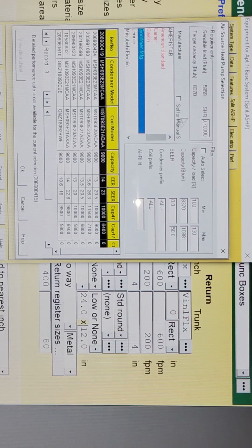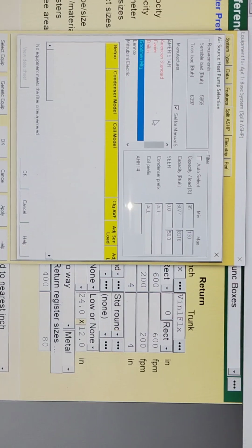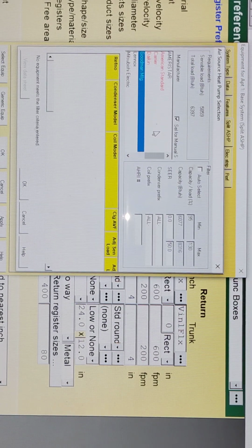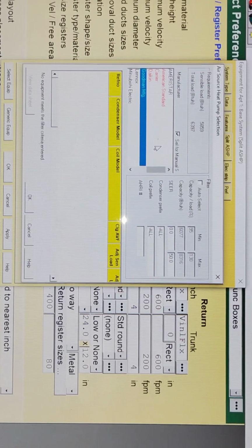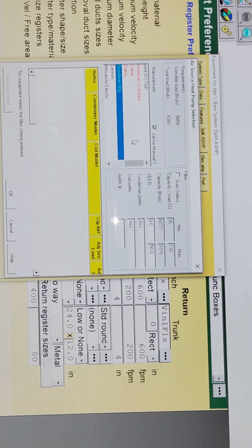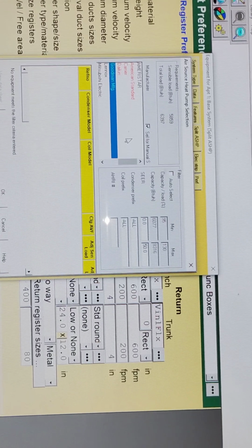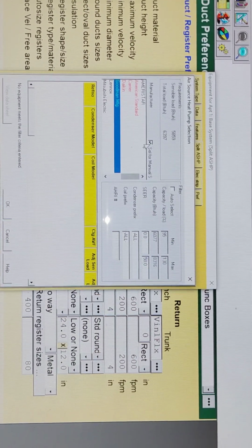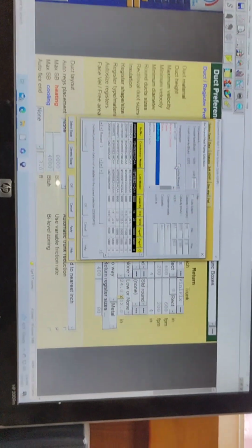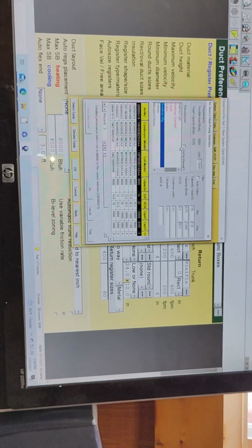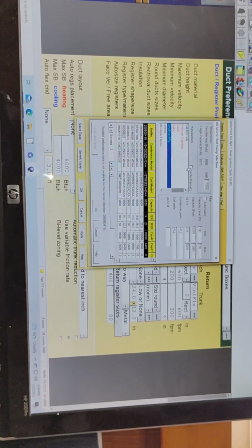As you can see, it's showing 5,000 to 8,000. We'll try to select for Manual S. So you see it's only 6,000 to 8,000 minimum and max. A lot of the time I have to look up this information in the manufacturer specs and then apply it to the program and select a lot of this stuff myself. Manual S basically says we have this amount of load with a sensible heat ratio of X, and that means our air conditioner has to put out X number of BTUs.